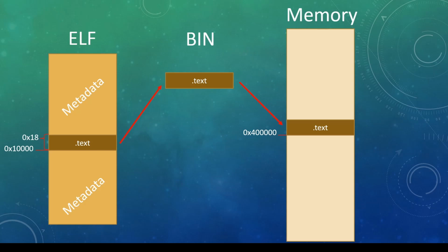Now, it depends on the architecture. There are architectures where programs have to be loaded to the right place in memory before they start running. And there are other architectures, for example AVR and PIC, where the CPU is executing directly from flash. In that case, we have to burn our flash with the proper memory layout in advance, and then during runtime they are just right there where they are supposed to be. And we will see that momentarily with an Arduino demonstration.